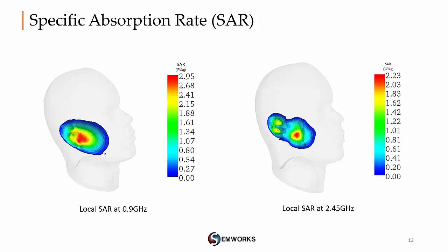We got the next SAR distribution results over the human head phantom, shown by the following figures. As noticed, both characteristics are not exceeding the restricted limits defined by the FCC, which is the Federal Communications Commission. So, the SAR value is highest around the human ear, where it faces the maximum of incident waves.